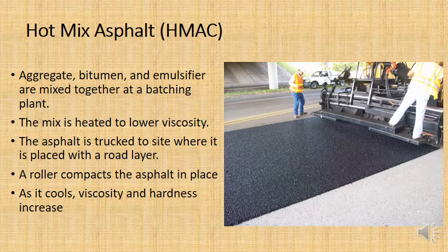So how do we get good workability between the bitumen and the aggregate? How can we place it on the road? Well, remember, you can mix the bitumen with an emulsifier, or in the olden days cut back like kerosene. But the other thing you could do is you could heat it up, and this would normally be heated up to about 60-70 degrees Celsius.